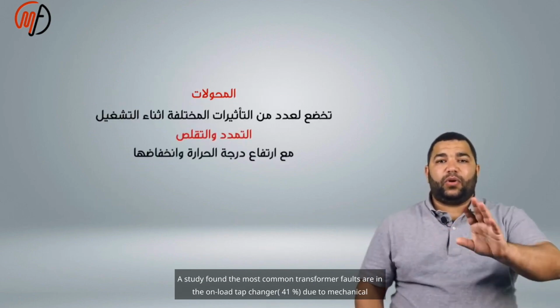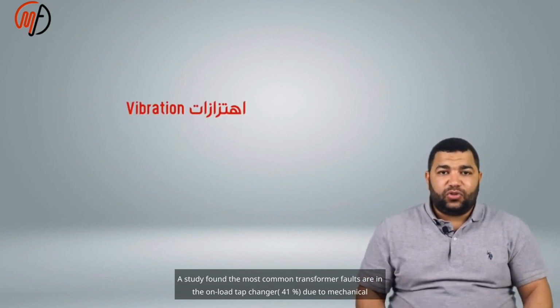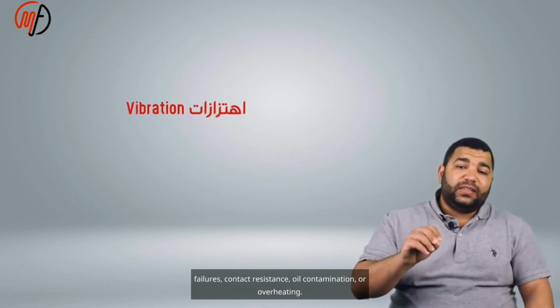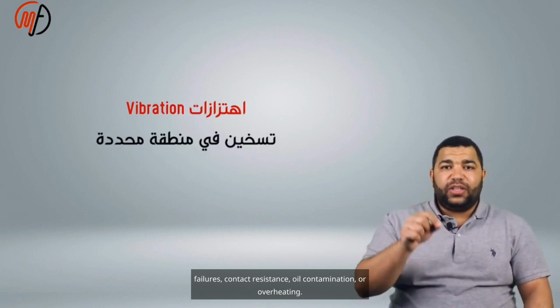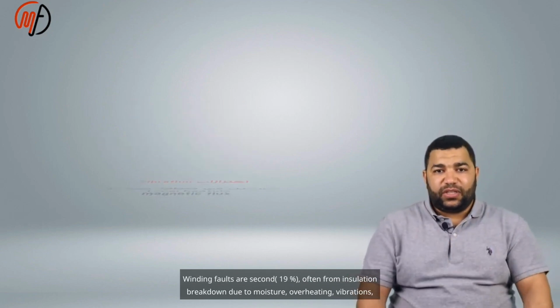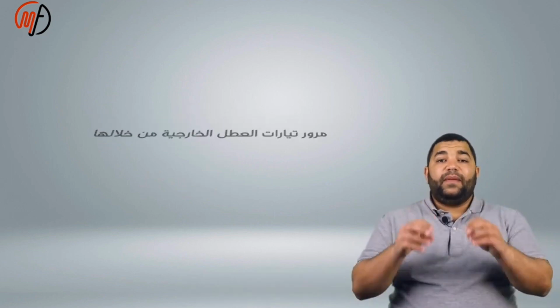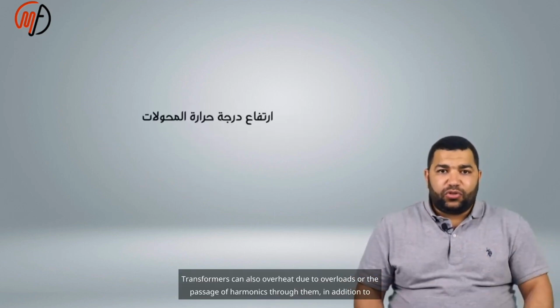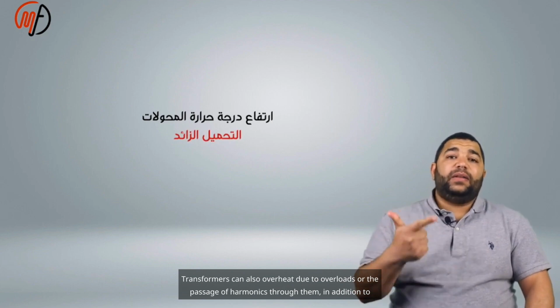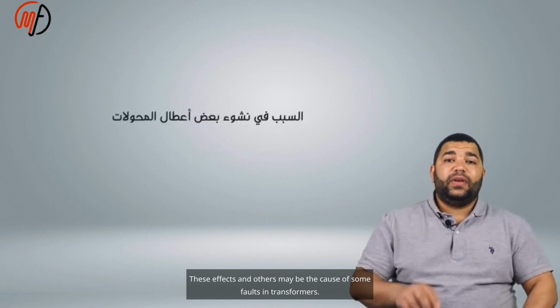A study found the most common transformer faults are in the on-load tap changer, 41%, due to mechanical failures, contact resistance, oil contamination, or overheating. Winding faults are second, 19%, often from insulation breakdown due to moisture, overheating, vibrations, or high voltages. Transformers can also overheat due to overloads or the passage of harmonics through them, in addition to insufficient cooling systems. These effects and others may be the cause of some faults in transformers.